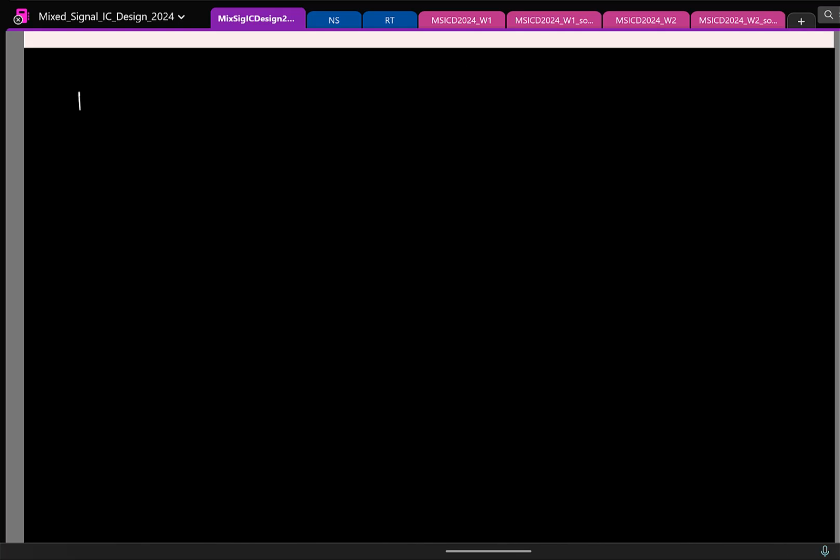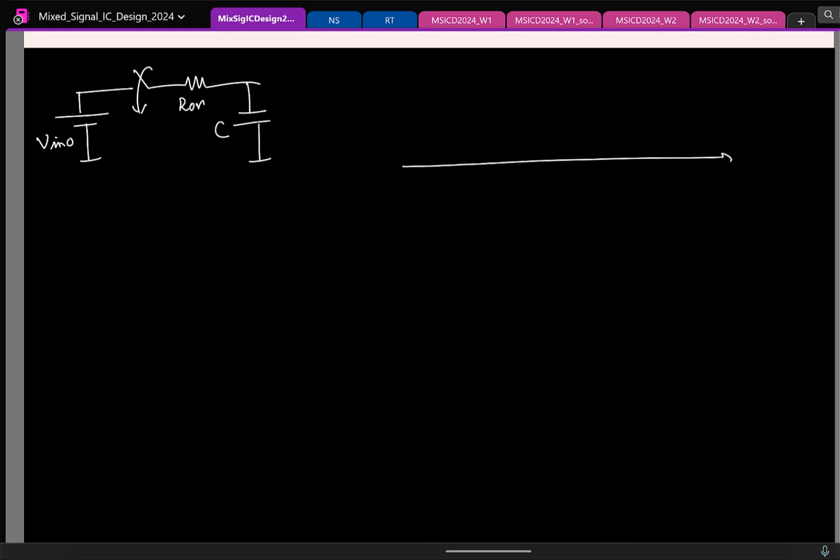So first we looked at a DC case, that is a constant. Let me quickly refresh this. Let's say it's some V in 0 and the switch is closed at some time instant equal to 0. This is your vanilla first order RC circuit. So the output will exponentially rise and eventually settle to the final value V in 0, right?